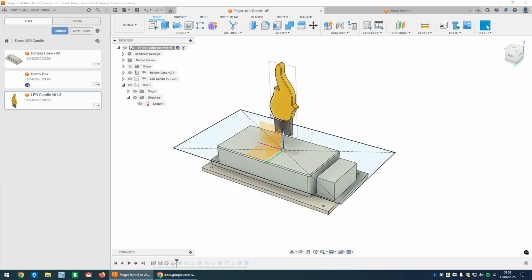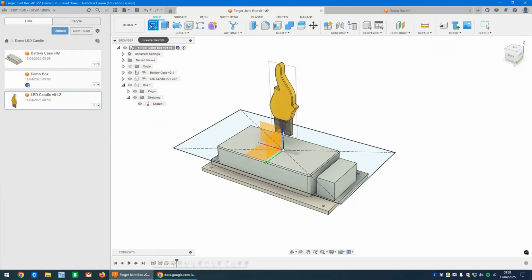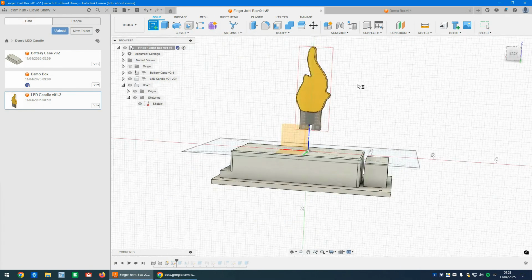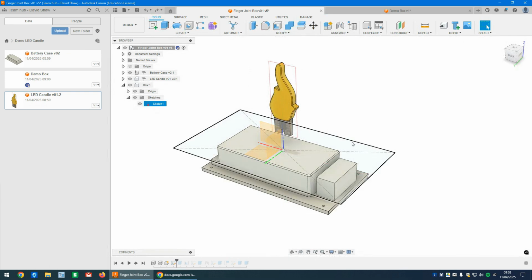And I've just created a rectangle here, center rectangle, based, so remember, sketch. Oh, it's in the sketch menu, excuse me. You need to make sure you do a center rectangle, not just a rectangle from the corner. From the origin, the dimensions for this, obviously, you're working out in advance before you come into Fusion.